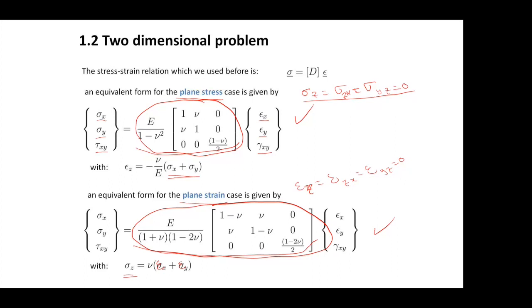All right. Now, if you look inside this, you'll see that it is a 3x3 matrix. There are 9 components to that. First of all, it is symmetric, so this is equal to this, and this one here is equal to this one. And second of all, it only depends on 2 things: the elasticity modulus and the Poisson ratio. It's just 2 independent numbers in there. Everything else is related to these 2 independent numbers.